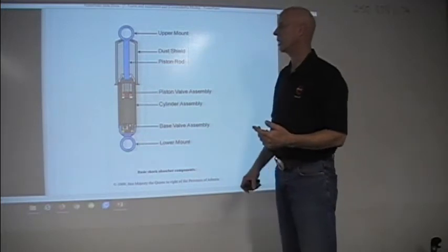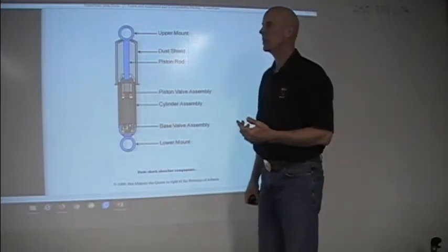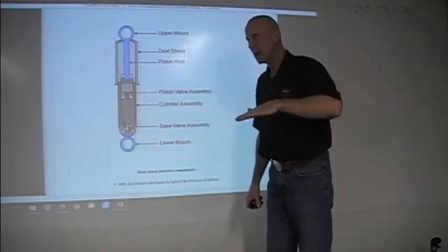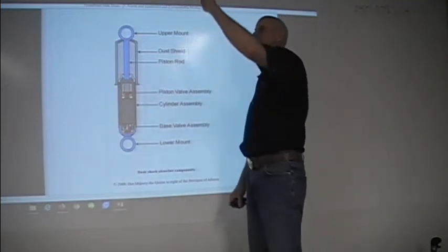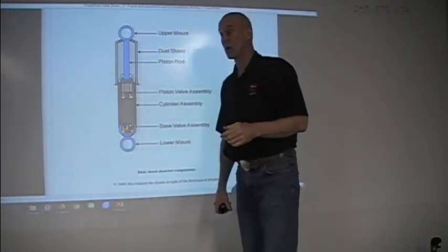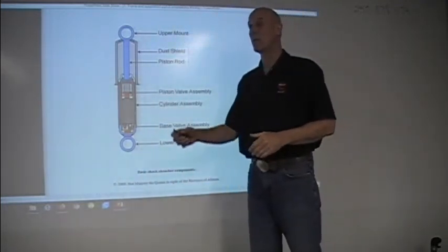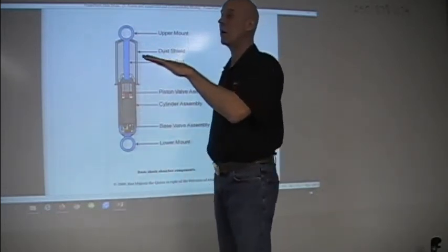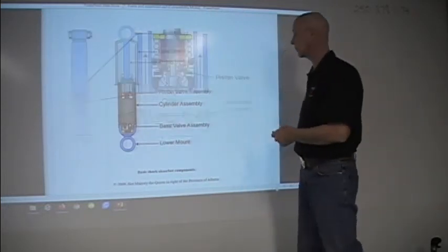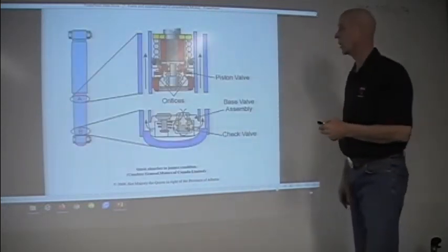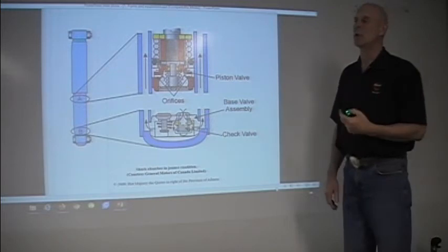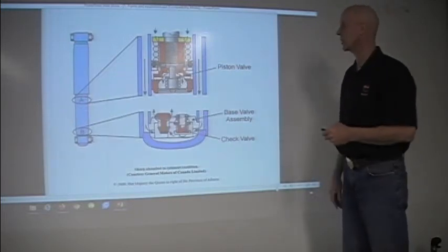Now, there's another thing in flying called wheelbarrowing. So when you come in and you land on your nose wheel, it goes up and it goes down, it goes up, and every oscillation gets worse and worse. In a case like that, I wheelbarrowed once in my life, and the first thing you have to do is give yourself full power. As soon as you start to climb, give yourself full power, and then you can settle it in. So we want to break that oscillation, and that's what a shock absorber does. And again, how they work is internally they control the flow of oil to prevent the oscillation from happening.